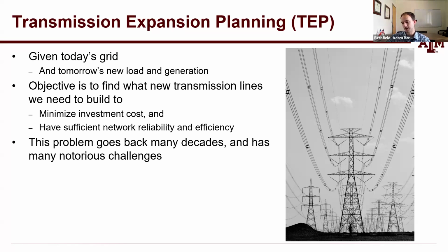I would say a lot of things are also affected by the specific voltage levels considered. So if you have a 500 or 765 kV network, your reactive power metrics are going to be very different from if your highest voltage is 345 kV, because with those higher voltage networks, you're going to have a lot more shunt capacitance and therefore a lot of reactive power supplied by your transmission lines. So that'd be a couple examples. There's a bunch more, but that's a couple of examples of how that goes.